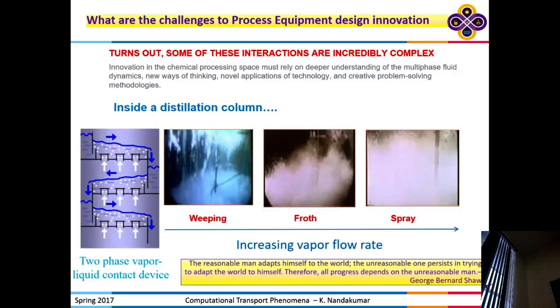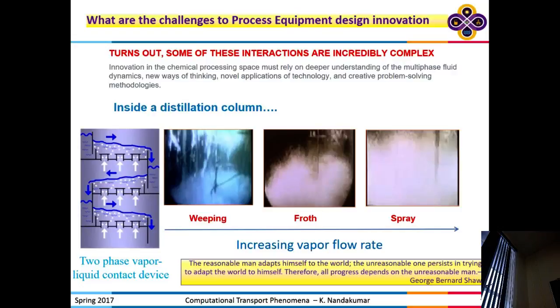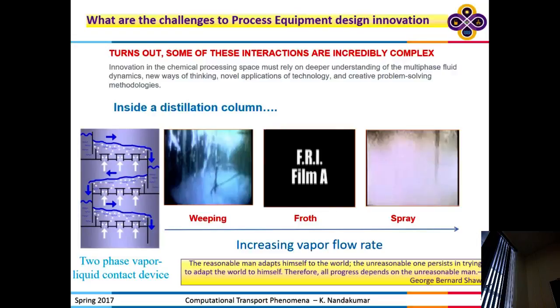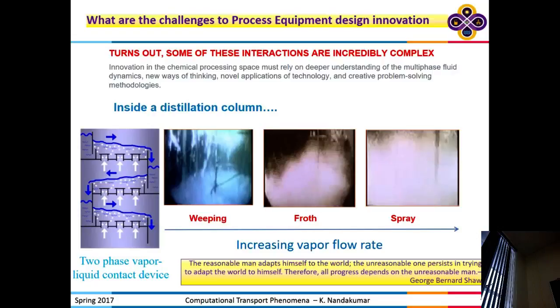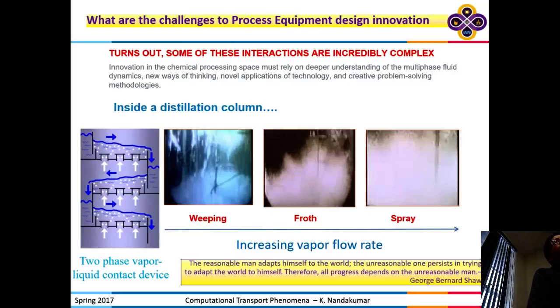And as engineers, what we need to develop is these clues. Like if you have the logic, you can then say, this might be happening. So I can do a simulation of heat loss when cold air is blowing across such a column. In Edmonton, in Canada, where I was, the temperature can drop down to minus 30 degrees. And they still operate these refineries under those conditions, right? So all these things can interact and create poor performance of the column, even though it is well designed to operate under ideal conditions.